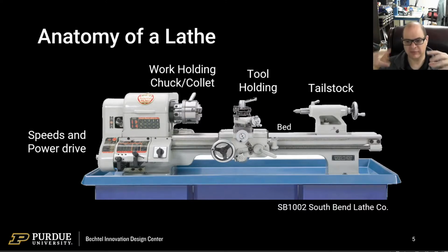And then as it's spun, although there's still an incentive for it to bend off center, it's held at both ends, so the end can't come free, and then you can machine much harder and in a much more consistent way. So please bear in mind that tailstocks are really important for any kind of long unsupported milling operation. So just to recap, motor and work holding on the left, tailstock on the right, and the saddle in the middle, which travels up and down that straight edge of the bed and carrying the tools with it.